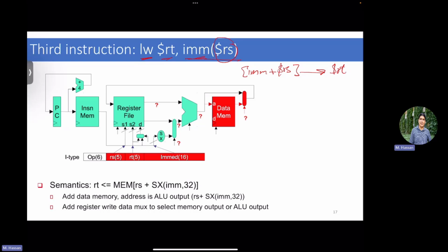It's very important to start with this because this is what will drive what control signals you have going forward. So for example, once I fetch my instruction, I understand it's a load. What do I need to do? Well, look for your sources, because the first operation is to read the source. I look into the I type, and I find my source in the same place. So that's simple. I already had the circuitry from before. I'm not doing anything. You'll observe that whatever we add newly is going to be in red, and anything else is just green and black. So this was there before. I'm not doing anything.